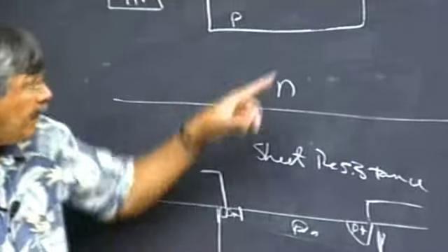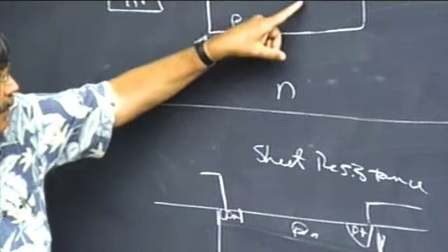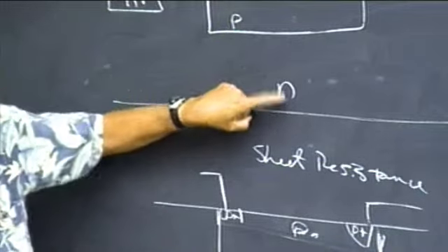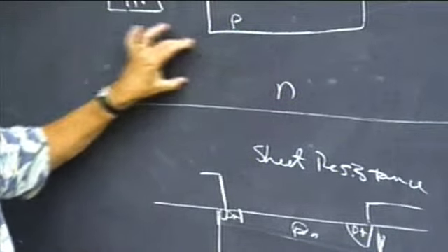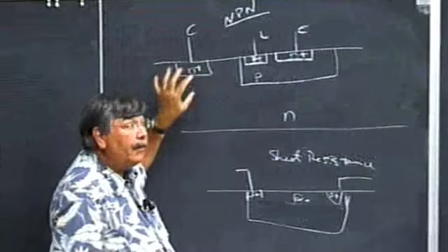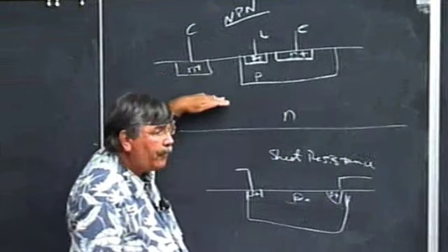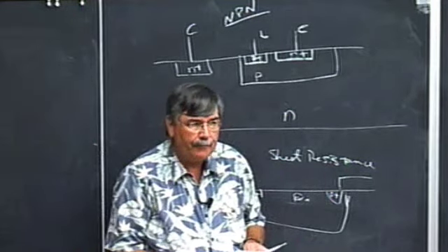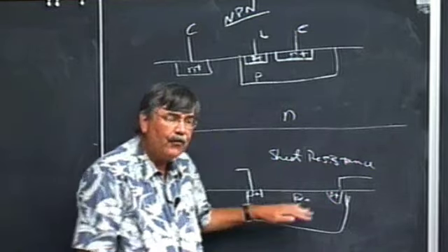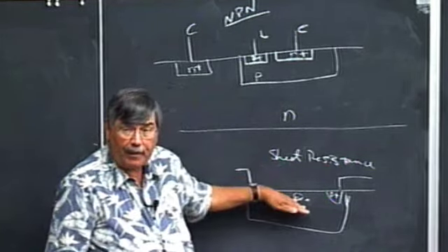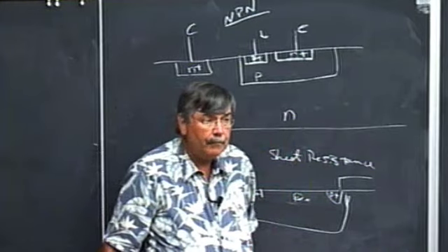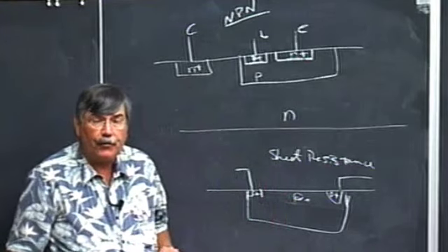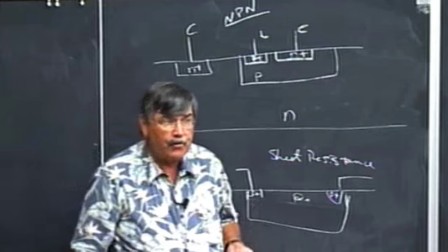So that's a trade-off. So if we have carriers that go from the emitter through the base and they get down into the collector, they're going to have to go through this. If this is lightly doped, then they've got a long way to go through highly resistive material to get where they're going. So one of the things we want to do is reduce the length of this path and have higher doping available. I'll show you what I mean in just a second. Are there any questions, though, about the concept of the relationship between the doping and the resistivity, and between the resistivity and the geometry, right? Longer distances with narrower layers means larger resistances.